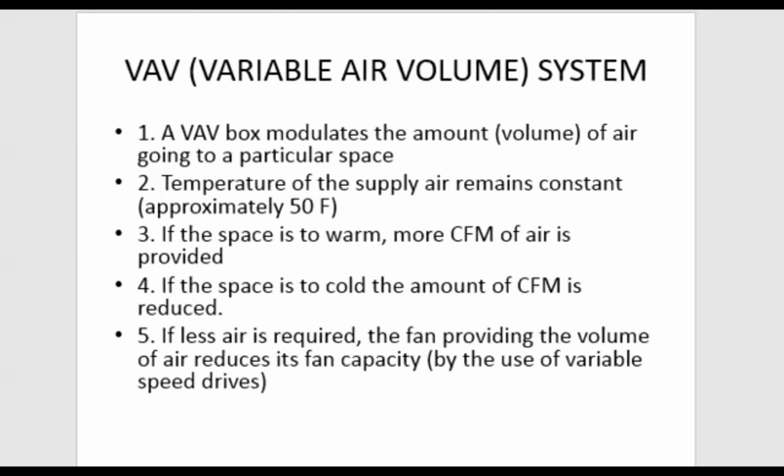The second version of this system, it's the same volume of air, so it's not variable, it's constant, but the system actually changes the temperature, depending on the source, wherever the air is blowing in from. It'll increase the amount of cool water or refrigerant or whatever it is that's cooling your air that's coming through the ducts. It'll increase that output so that the air is cooler coming out of the ducts, and it'll come at the same volume at all times.